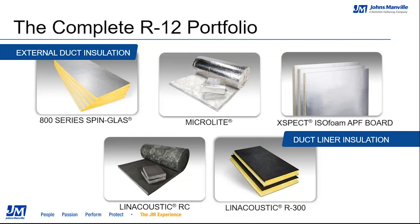So what does that mean to you, Mr. Engineer or Contractor? There's a specific application this product is utilized in. This product is a closed cell product, by the way. It's a polyiso foam product with double layer foil on both sides of the board. It's a very durable and rigid product. This X-Spec product provides a moisture resistant vapor barrier that is being used more and more to insulate rooftop ducts because of its R12 nature at 2 inches thick and its overall durability.